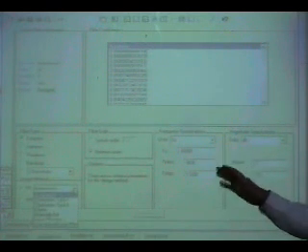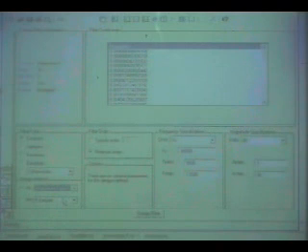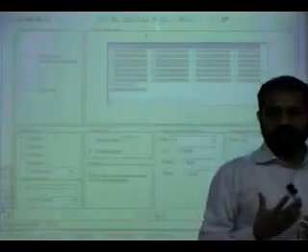Then you say, no, I don't want a Butterworth. It does not give you the option to use a bilinear or an impulse invariant. We could always use this bilinear. Right? So it does not give you the option. It says bilinear. Now you can say Chebyshev type 1, and we know what will happen in Chebyshev type 1. Okay? So you say design, it definitely will give you the same design in a fewer number of coefficients. It says now only 13. Okay, and we also know where you will see the ripples.